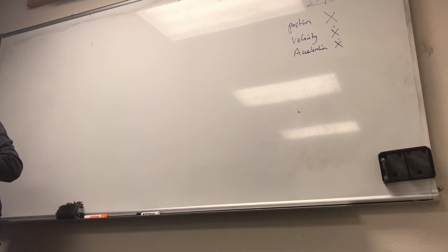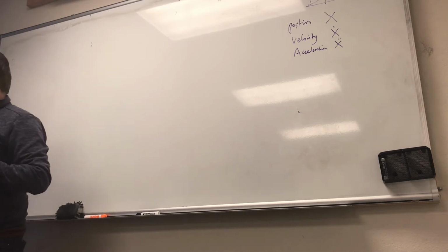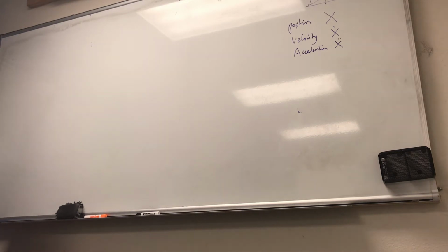What do you think harmonically means? Around a natural resonance there so that it couples, right? So a harmonic is like you're exciting it with a function that has an omega in it. It's like a sine function or a cosine function. That means you're exciting it. Some of the forces, instead of saying it's equal to 0, is going to be equal to maybe some F cosine omega t or something like that.